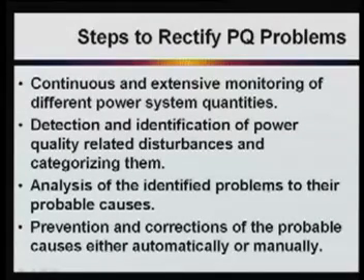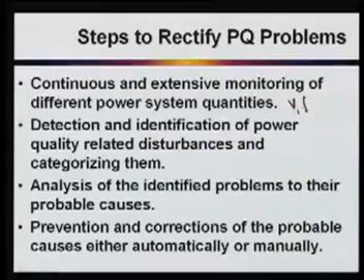Now once you have monitored and collected the information for these power system quantities, that is your voltage, frequency, and the current if you are measuring, these three quantities can give information about all your PQ problems, or you can say disturbances. Once you have measured this, it is our duty to detect which type of power quality problem has occurred.